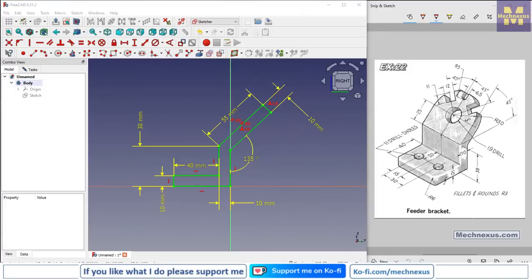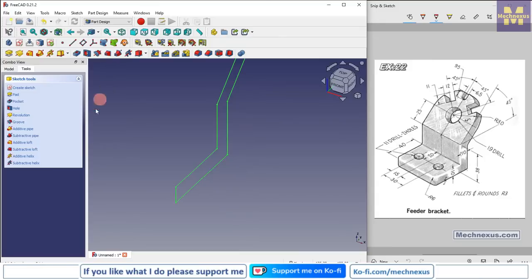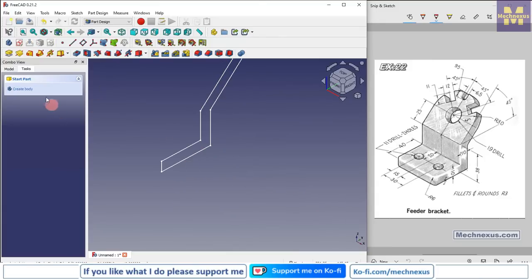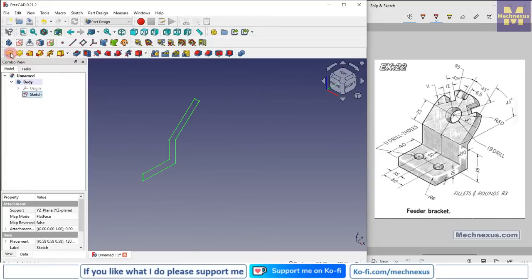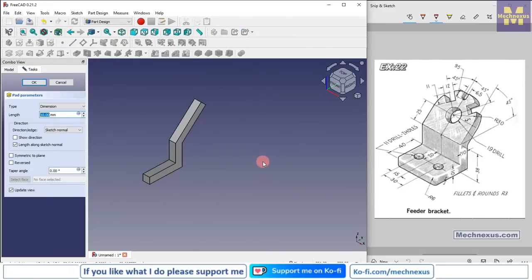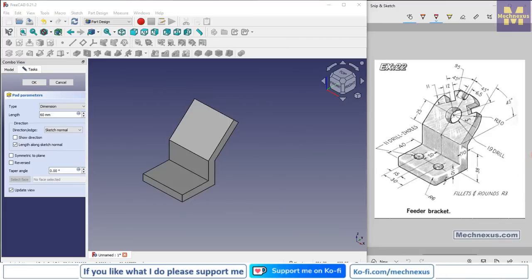Now we will extrude it. We will come out of the sketch, press 0 for isometric, switch to the model tab, select a sketch, click on extrude, and extrude to the distance of 60, and we will keep it symmetric to the plane.